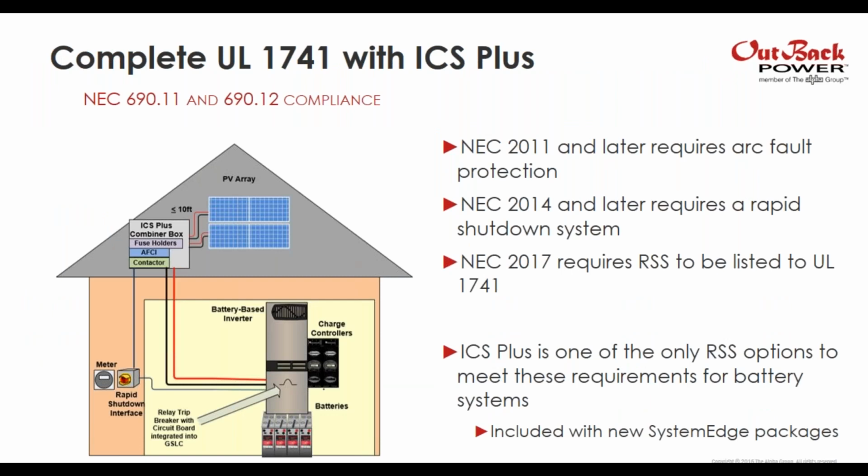So as I mentioned, all of these new systems come with our ICS Plus rapid shutdown system. And the nice thing with the ICS Plus is it's got everything you need to make sure that the installation complies with the latest iteration of the NEC. So 2011, you have to have arc fault protection. That's in there. 2014 introduced the rapid shutdown requirement. That's in there. 2017 tightened up that rapid shutdown requirement a bit, and while this isn't module level, that's not required until 2019.